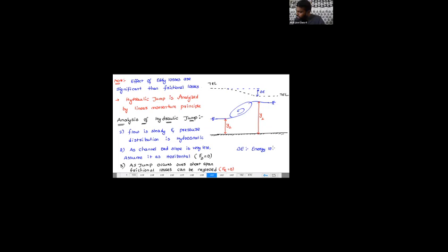And this energy loss is due to whom? Eddies, not the friction. Where Y1 and Y2 are known as conjugate depths or sequent depths. See, I told you why. In the case of the same specific energy, I told you these are the alternate depths.